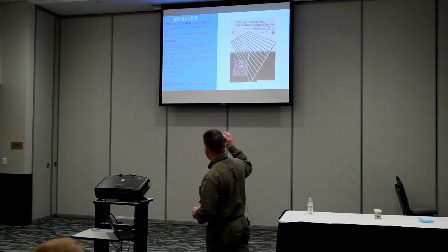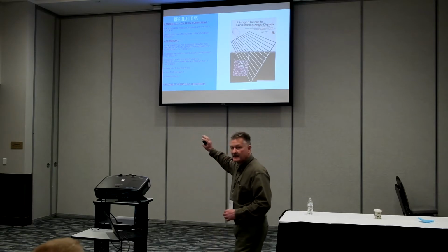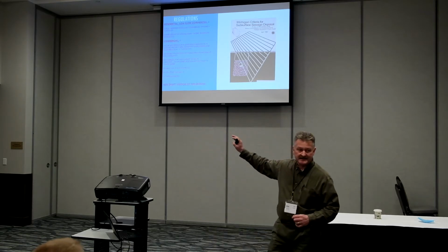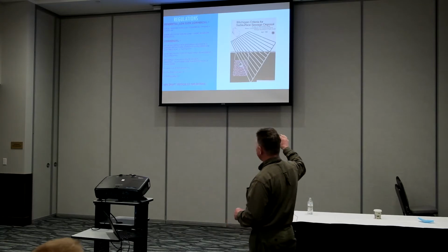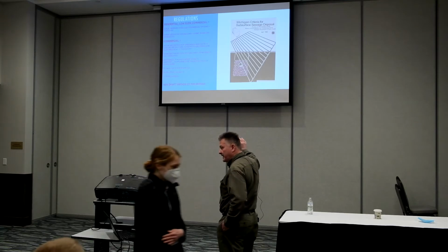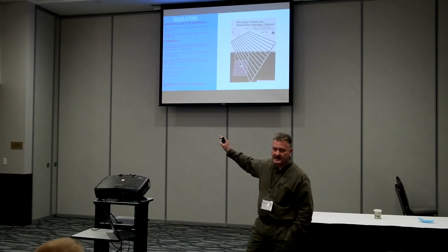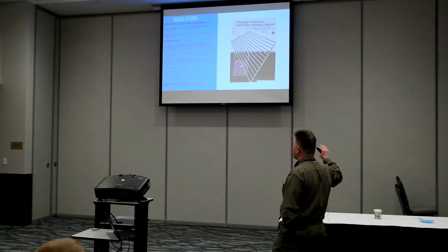But again, your sanitary code's only addressing the flow volume, and we size everything by the hydraulics. And then we go into larger commercial flows, less than 10,000, then we're going to be applying the Michigan criteria information when we're designing that system.